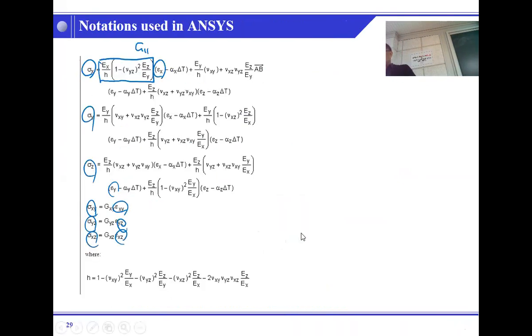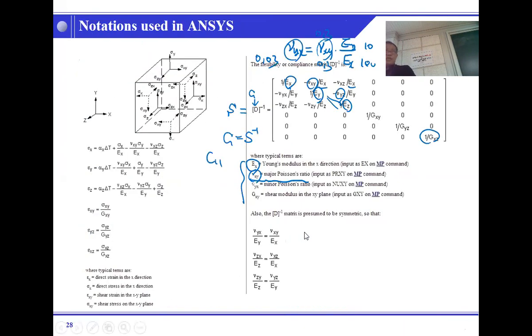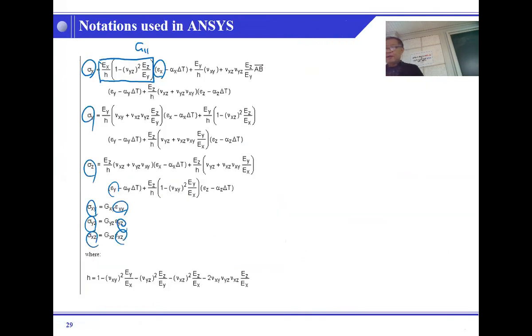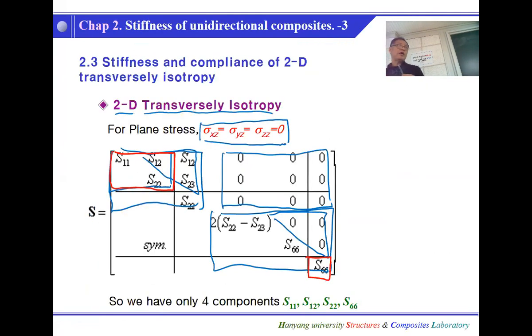You can always come to the reference and refer to all the 3D definitions, but most of the theory which we will cover in this course is called classical laminate theory. We consider only very thin plies and stack them together. So sigma ZZ, ZY, ZX can be neglected. But in an advanced course, those 3 terms can be huge. I will cover that at the end of the course, but for now, we just consider only plane stresses.